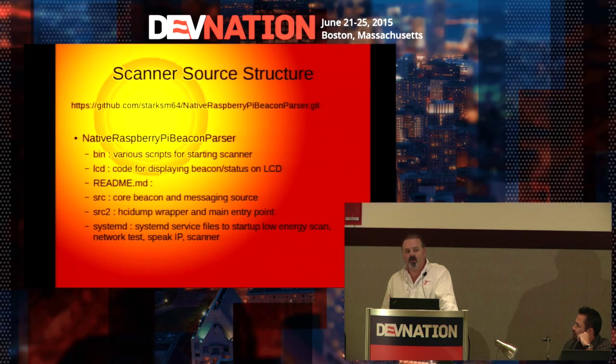There was a battery test mode, so that we could see how long the batteries in these things lasted, because it's actually not that great. Typically, it's going to be 6 or 7 days before the beacon runs out of power. It's not that great a sensor relative to what you would typically expect. Some of the more expensive beacons add much longer battery life as a feature. For example, Gimbal also has a $20 beacon that they claim will run for 3 years, versus 6 days. This beacon is particularly bad, and I think they actually have some firmware issues that they acknowledged when I originally asked why the battery life was so bad. I think there are firmware issues that they could improve upon.